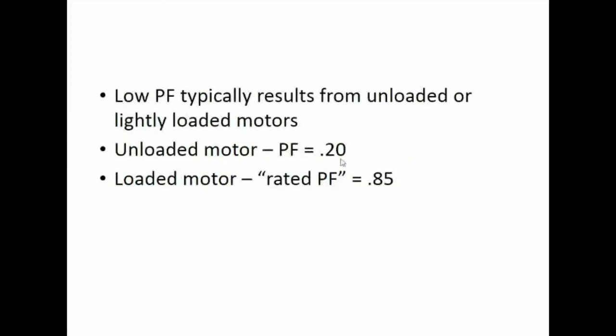The low power factor typically results from unloaded or lightly loaded induction motors. For an unloaded motor, the power factor will be 0.2 to 0.36. A loaded motor will have a rated power factor ranging from 0.8 to 0.9.